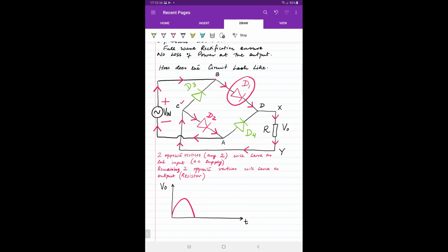Yes, you have written it correctly. So, so far, for the first half cycle, everything shown with the red marker is valid. And the diodes D1 and D2, the two diodes opposite each other, both of these diodes are conducting. So the first half cycle is concluded at this point, and diodes D1 and D2 have conducted during the first half cycle.